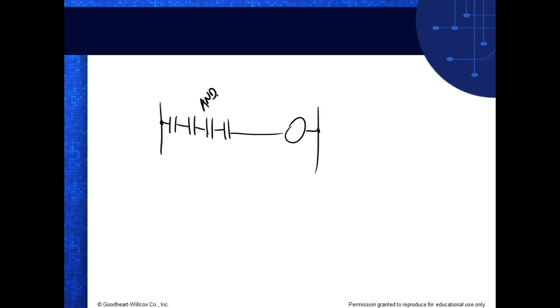You're right, they are in series, but what we're doing is logic. Now, if I come over here and start putting contacts in parallel, that's an OR, and we use the term any. So if any one of those contacts is closed, then we say it's an OR, right? Just saying what the contacts do can almost tell you if it's an AND or an OR. ANDs and ORs are what's required to energize the load.